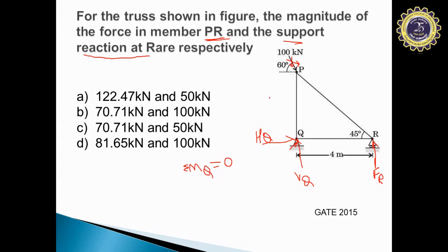So that is one of the easiest ways to find out whether you are putting the direction of the resolved forces in a proper way or not. You should go to the back end of the arrow, draw a plus mark, see where the arrow is lying, and simply take the two directions of the x and y axis where the resolved forces will go. Now that we know the direction, this is one direction and this is another direction. Yes or no? So now it will be acting here.